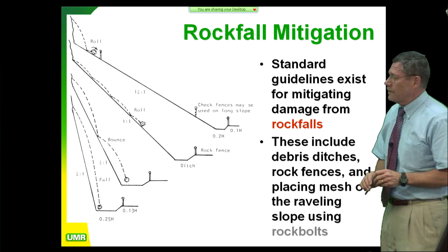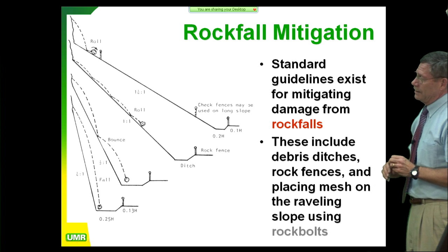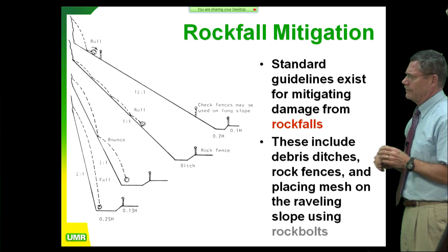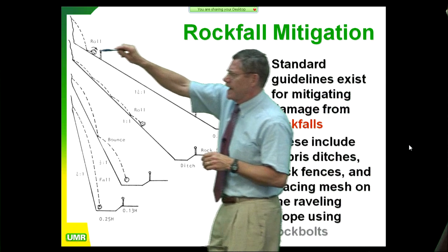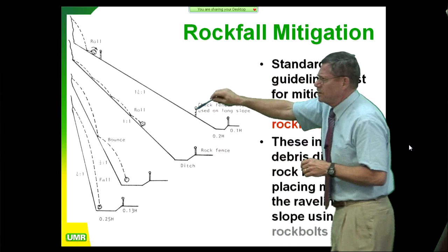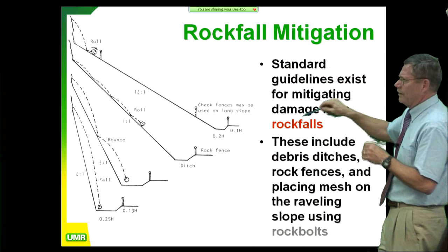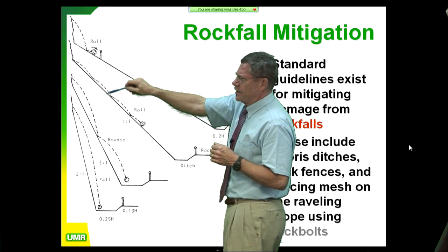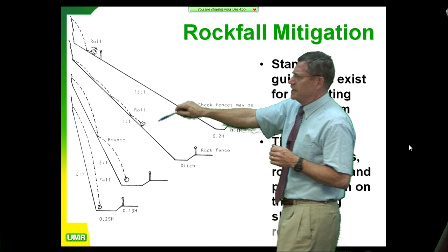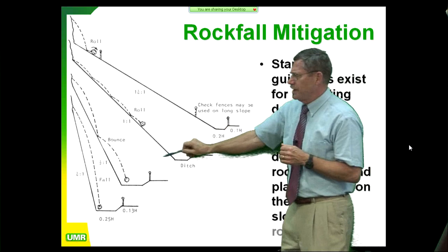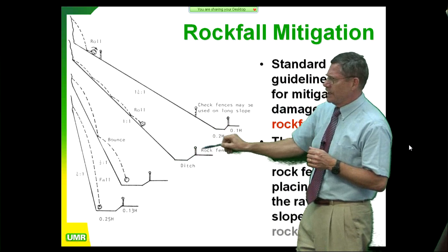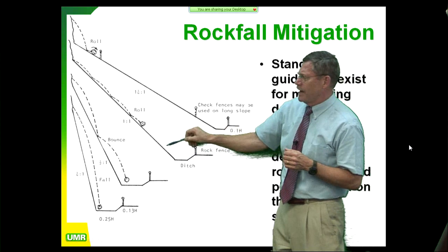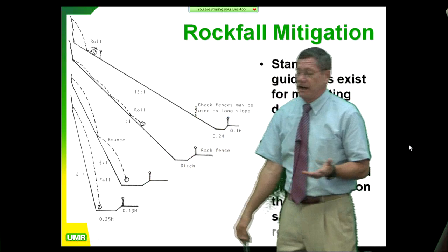There's all kinds of rockfall mitigation programs out there. Almost all of them that I know of are very flawed. A lot of them are way over-conservative. They show blocks that are wholly elastic that just bounce around like baseballs from a ball game and come way out here. In reality, there's a lot going on with energy dissipation with each divot as these things go in. But basically, you've got to have some place for them to go down here where you can get behind this barrier and muck this material out periodically, because it's a maintenance headache.